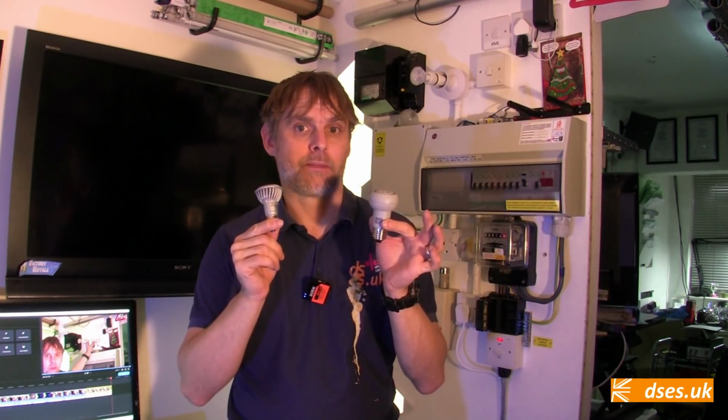But while incandescent lamps are all largely made equal, we've already seen today that LED lamps are not. An LED element itself typically only requires 2 or 3 volts of DC to operate, so to make a lamp which is bright and can run from 120 or 230 volts AC requires some kind of circuitry.